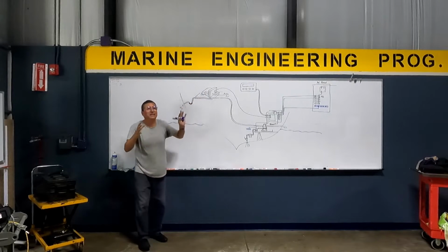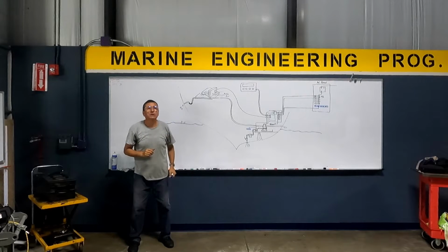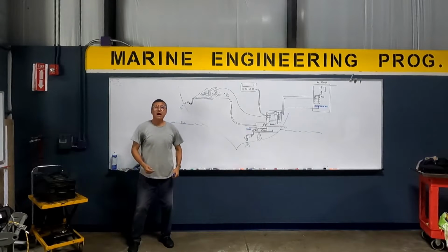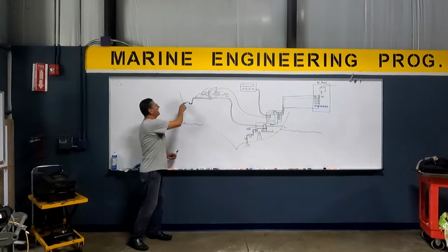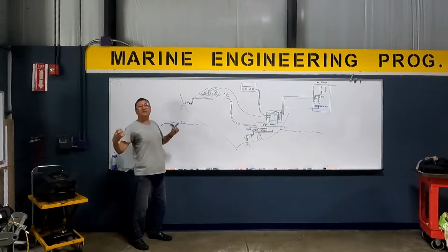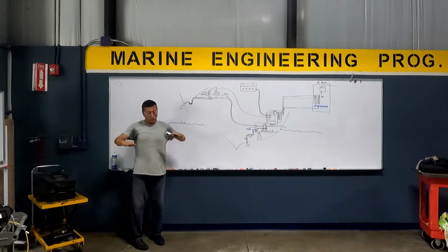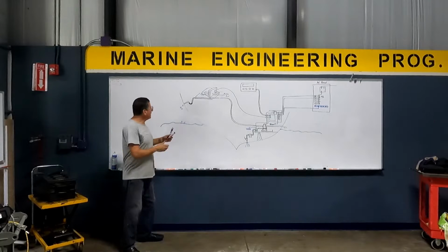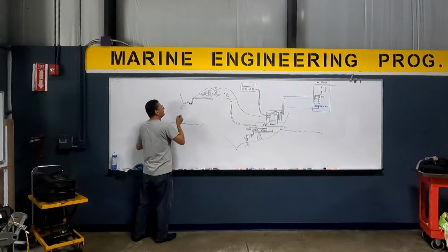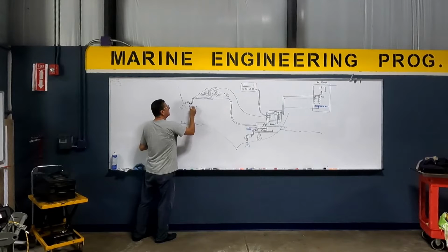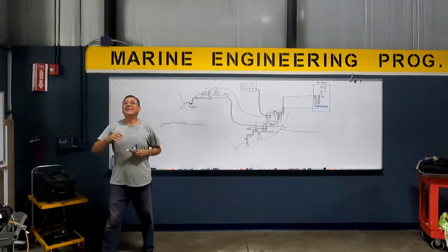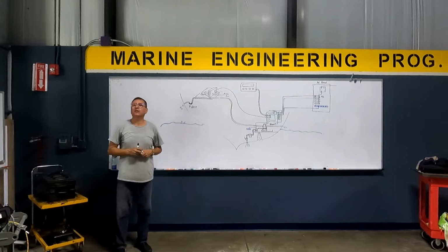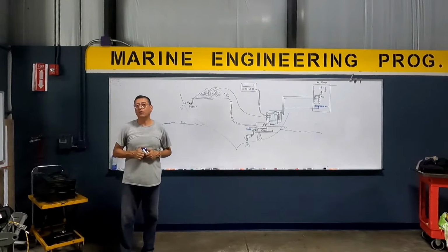Where is that unit located in the typical small and medium boats? Bedroom, the cabin. Behind the bed, under the bed, in that corner. What happens if gases, carbon monoxide, are entering here constantly because the exhaust pipe of the generator is pretty close? You die in your sleep. You get sleepy. Finito. Everybody follow me? What is the name of that element? P-trap. Where is it located? By the outlet. It is the drain of the evaporator unit, and it drains fresh water, not salt water.